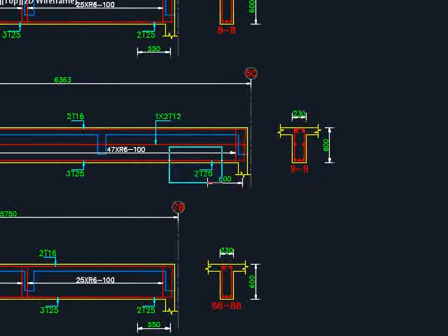Do some necessary curtailment where you have 3 T25 at the midspan. Now you have only 2 T25 near to the support. Clearly indicate where you can cut that additional T25.